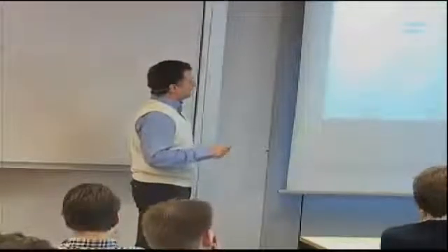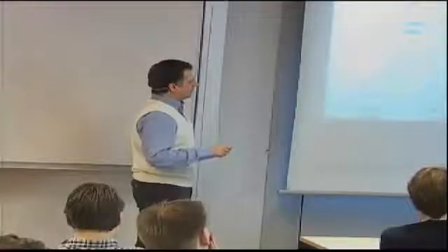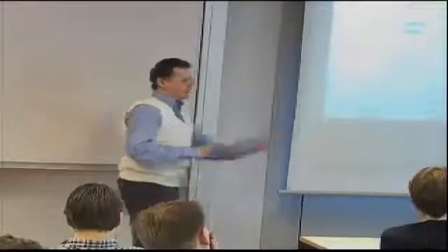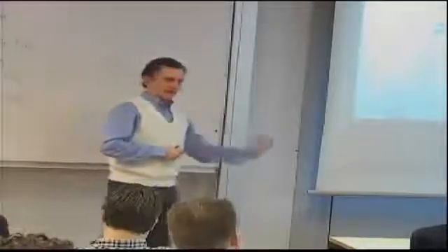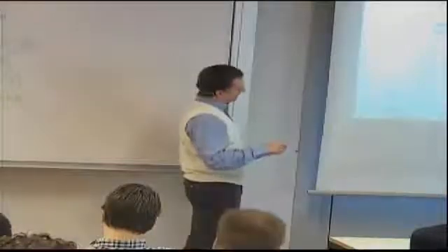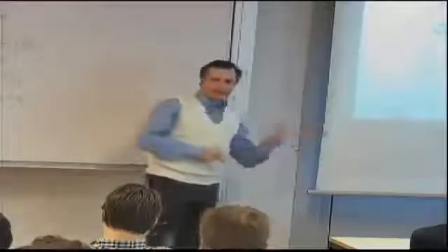Imagine the skin here between these two stiffeners. When it buckles, this part is meant to come towards us. And this portion is meant to indicate that it's going away. It's the half wave moving away. That means the skin itself tends to pull itself away from the stiffener, so you develop out-of-plane loads. We'll see those later on in the course.